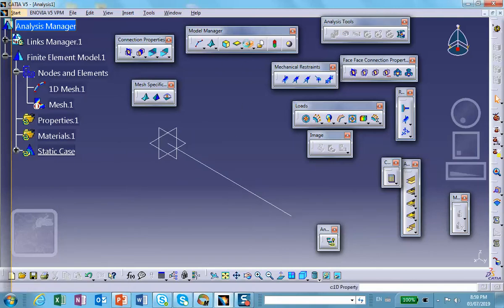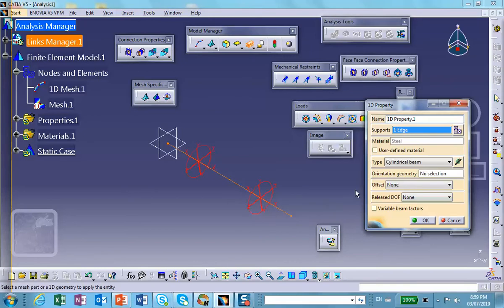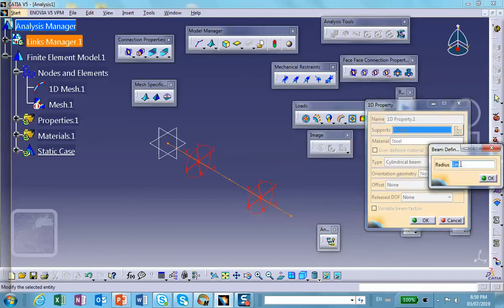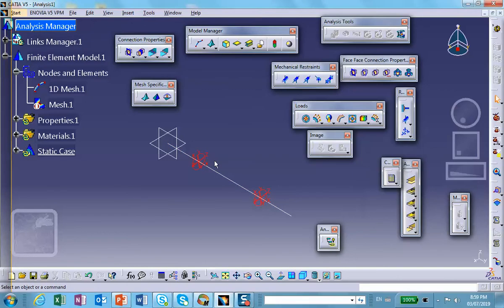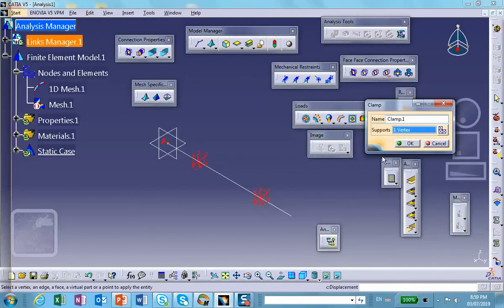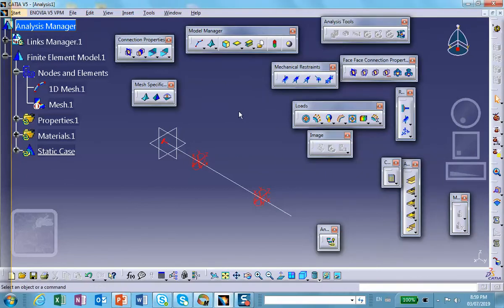Select this. It is circular, and the radius is 0.5 according to my MathCAD worksheet. Okay, and because the cross section is circular, you don't have to select an orientation point, and you can just close this. Okay, and what else do we have? We have this end clamped, meaning no translations, no rotations, and we have a 200-pound point force right there at that node. Or at that point actually, this junction point is right there.